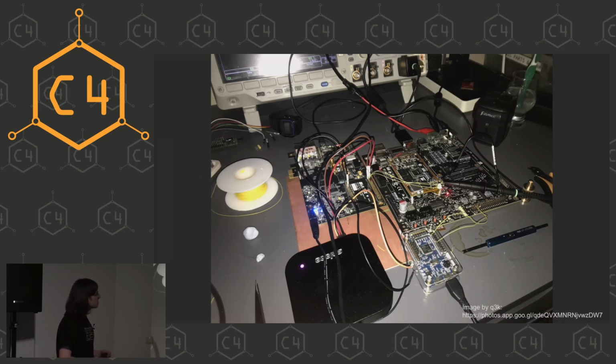Yeah. So we wrote a script that did this loop where we glitched it, we looked at the output, we reset the board and adjusted the time, reset the board and repeated, and left this thing running overnight. We just recorded everything our code spit out on the serial console. The next morning, we looked at the dumps and we saw that at one place, it actually started dumping. It said, well, that register is still the reset value and here's the ROM. But it wasn't the ROM. It was still that EF, whatever, jump to zero thing.